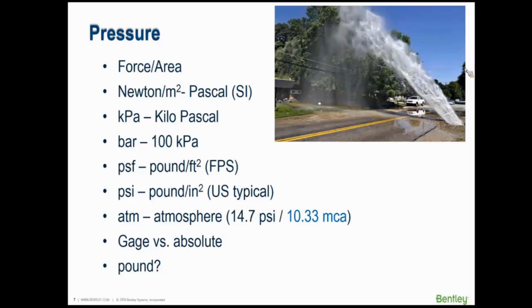Now, pounds can lead to some misconceptions. I heard a story one time where this guy decided he was going to save gas in his car, so he was going to let a couple of pounds of air out of each tire, and that way his car would be lighter. So hopefully you see the fallacy in that argument and a reason you shouldn't say pounds when you're talking about pressure. You should say pounds per square inch or PSI when you're talking with somebody. But people do use pounds a lot, so just be used to that.